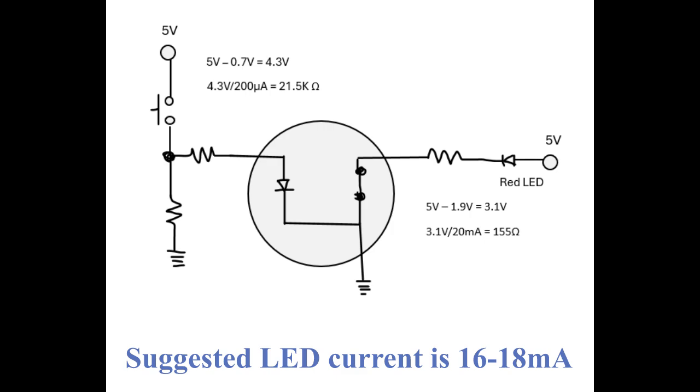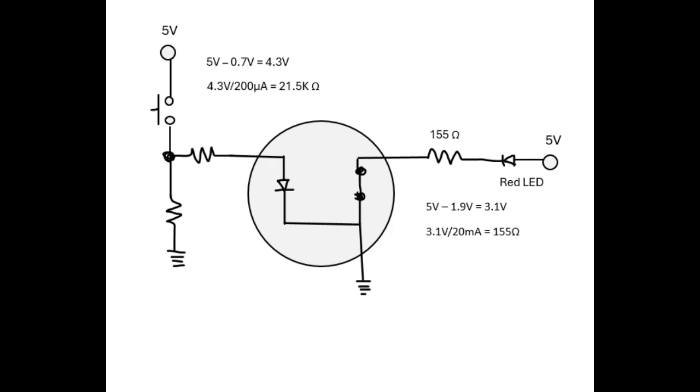Now, if you take 20 milliamps divided by 100, you'll get 200 microamps. 200 microamps is what will be needed to make sure the transistor saturates or is fully activated. Using a typical gain of 100 is significantly less than the actual gain of the transistor. According to the datasheet, as I mentioned earlier, the gain is between 30 and 300. Using a gain of 100 almost always gets a transistor to saturate or become a switch and pass all the current necessary to drive the load.